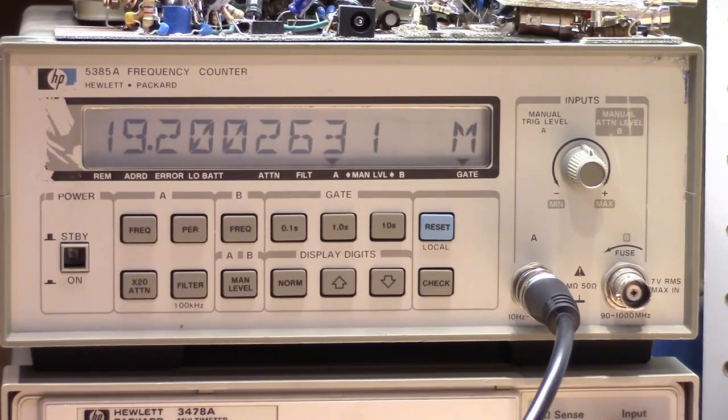All right, well, there you have it. That's a full 10 minutes. And this thing drifted about 1.5 hertz in the first minute, and a grand total of 0.2 of a hertz over the next couple of minutes there, and it's just been rock solid here after the first 2 or 3 minutes. So definitely very good stability out of this, and very little drift at power on, which means we have very little power dissipation in the crystal, which is excellent.